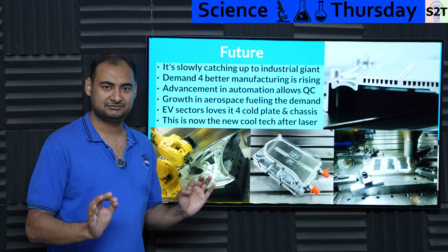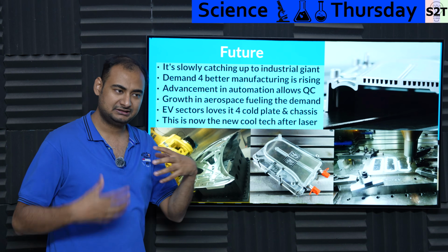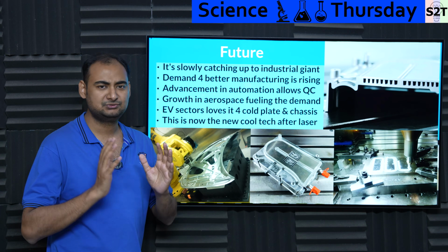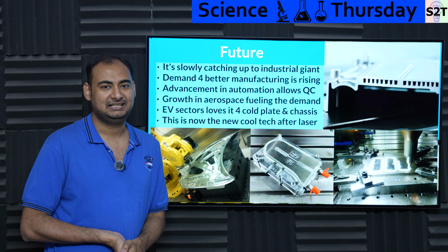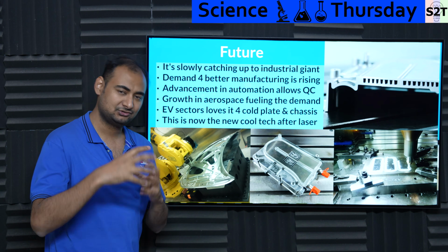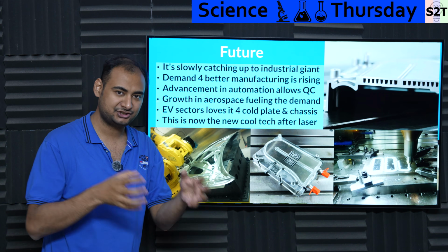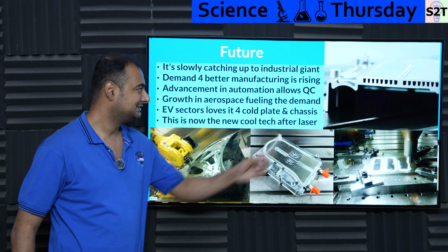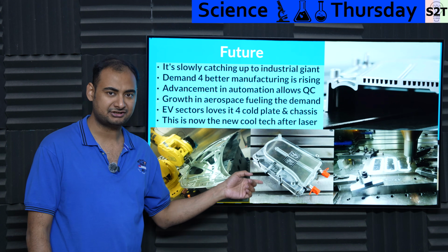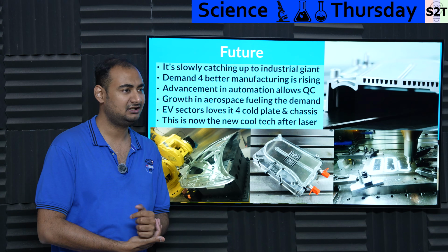And power electronics, they love this. Because again, if you want to run basically a lot of coolant, you need to have pressure in some scenarios. Again, depending on the pump requirement and the cycling requirement, you may require it. At that point in time, you'll be like, okay, what the hell? If you have normal laser welding, it is very likely to break apart and all that. In those sorts of scenarios, having extruded aluminum as your main structure or die injection as your main structure, you need to seal it up. Friction stir welding is like, I got you. Surprisingly, a large amount of electric vehicle inverters have this. I was thinking, okay, aerospace, I saw this. I was like, no, electric vehicle, they're loving it.